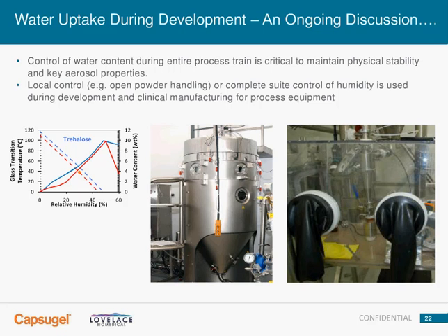Again, revisiting water content. I talked about the formulation and excipients. If we go through the process of picking our excipients and understand the water content after spray drying, we need to pick the relative humidity that hits that desired water content from a glass transition temperature that gives us a physically stable product. In a lot of cases this is done with either local control shown in the picture here or with sweep control. Typically, relative humidities of 30% or lower is what might be required in the spray drying process and handling using hygroscopic amorphous materials.